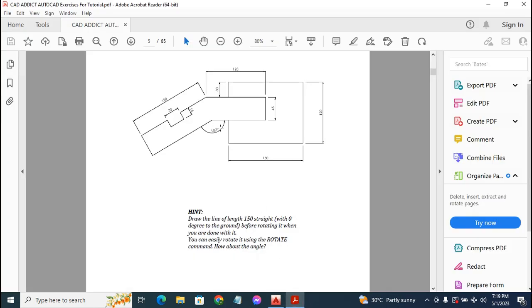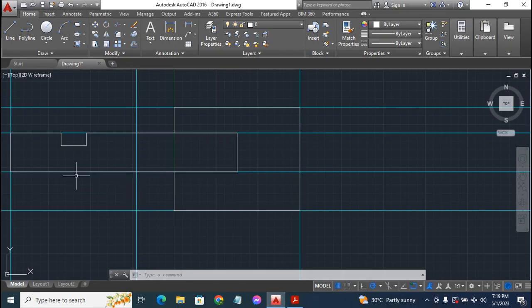The next up is to get this angle. We have to incline this other rectangle at an angle of 150 degrees. So how do we do that? Looking at this drawing, from this very point, if you consider this vertical construction line and this horizontal line here, you agree with me that the angle between these two lines is 90 degrees. The angle that's supposed to be between this line and this third rectangle with this indentation is supposed to be 150 degrees. So since we already have 90 degrees, you take away 90 degrees from 150 degrees, what will be left? Yes, 60 will be left.